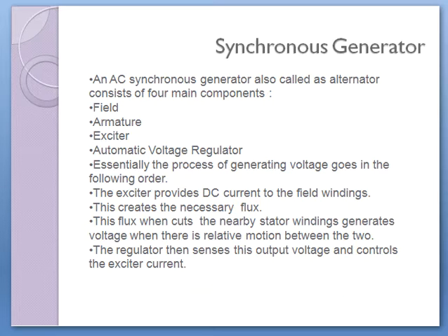The strength of the magnetic field produced is determined by the amount of current passing through the conductor. When a stronger magnetic field passes a winding, more current is produced in the winding. In a generator, the amount of current produced in the winding can thus be controlled by controlling the amount of current passing through the conductor that is causing the magnetic field.